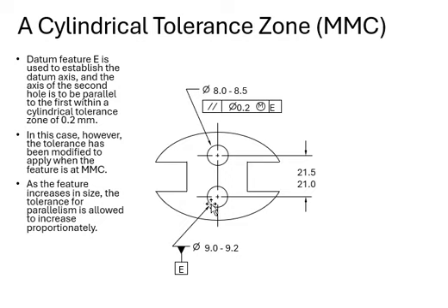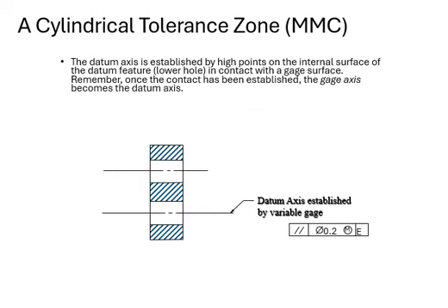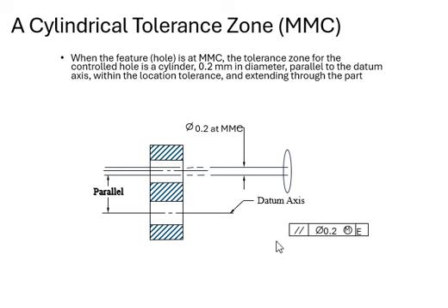Of course, with the front view, it's really difficult for you to see it, but on the side view, we can see the two holes right there and two axes right there, and your datum axis established with your gauges right there, and your control frame is right here controlling that. And we go back here, and now we put our zone right there, so you can see this little circle right there to point out that we're dealing with the diameter tolerance for this.